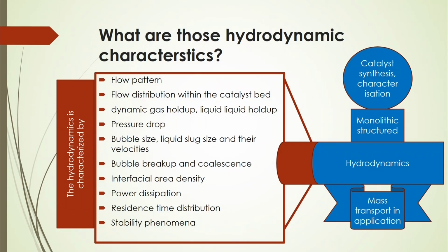And for liquid also we are getting different types of flow pattern, and for gas, liquid, solids, 3 phase also, we are getting churn, turbulent, homogeneous, slug flow, plug flow, and particulate flow. There are different types of flow patterns. So, those flow patterns actually will give you different types of mass transfer efficiency, even reaction performance, and then overall reactor efficiency for that particular chemical engineering process.